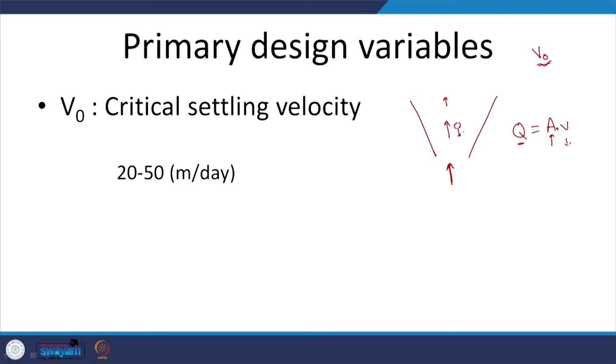So here we see this is the settling velocity of the particle, which we calculated from Stokes law earlier, and this is the velocity of flow of the fluid. If the settling velocity is higher than the fluid flow velocity that is taking the water out, then obviously the particle will settle down. So if Vs is greater than Vf, the relevant particles will be removed, 100% removal.